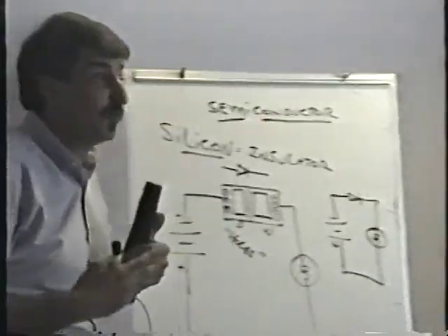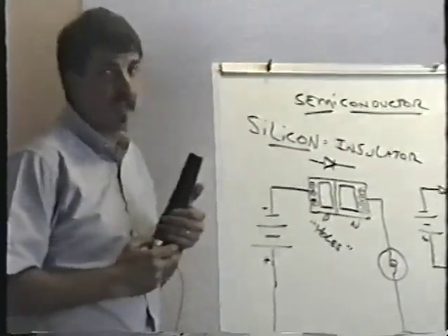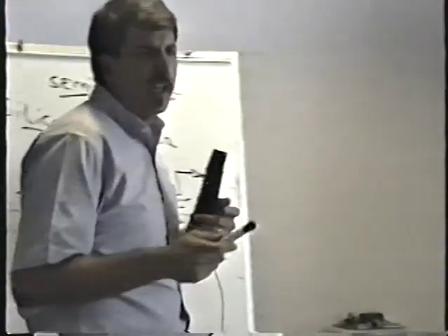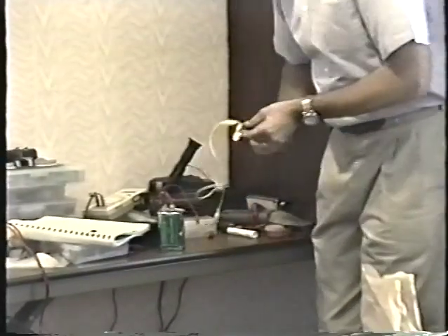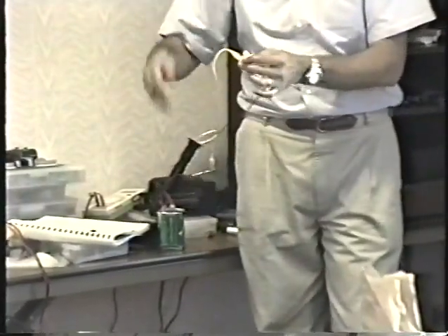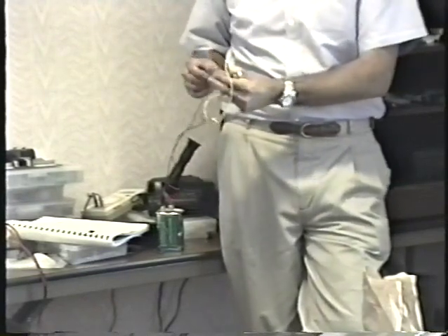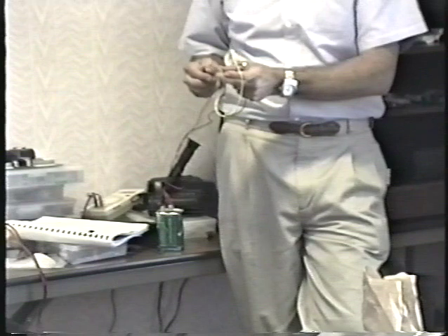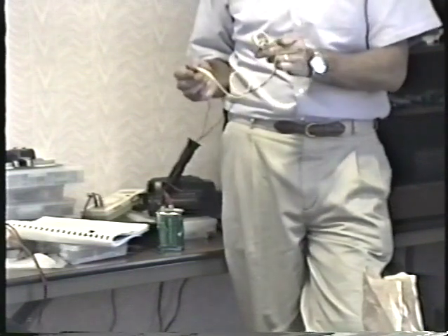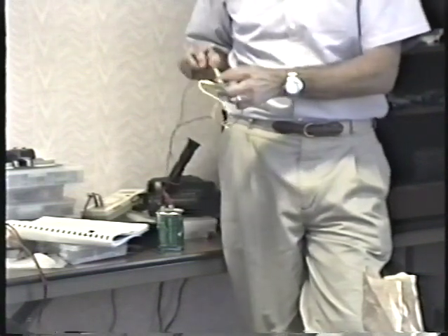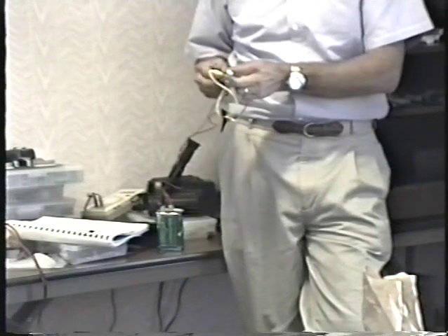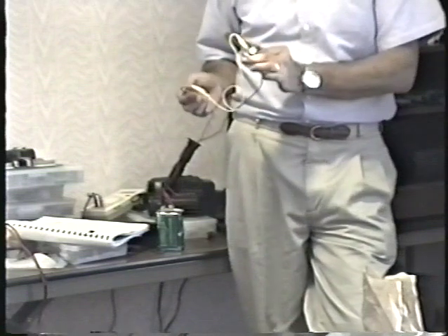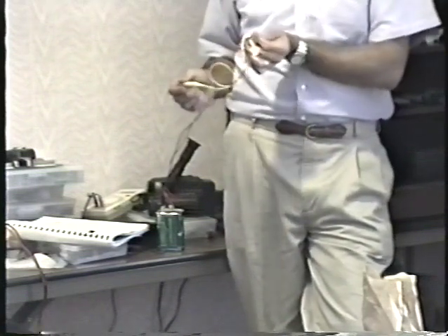You know, but that's how it was explained to me at one time. It's like, well, they kind of conduct, but they really don't do that good a job. Well, that's nonsense. Look, this thing is on. This light bulb is definitely on. There's no question about it. And yet, when I reverse the diode, it's completely off. It's completely off or it's completely on. One or the other. So it isn't like it does a lousy job of conducting. When it's conducting, it's doing a great job.